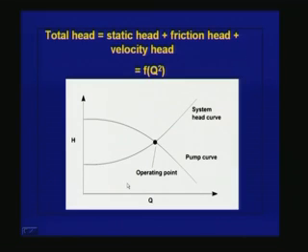Another important factor in the pump selection is what we call the operating point. The operating point is the point where, when you take a pump and put it in a system and start the pump, it will tell you what discharge you will get and what head is developed by the pump. Remember, the head developed by the pump should be such that it gets over not only the static lift but all the frictional losses and the velocity head at the delivery point.